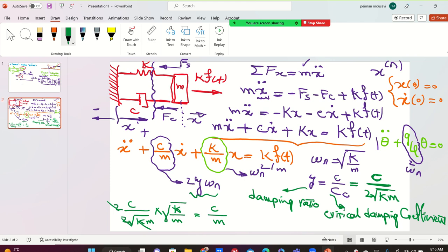You see that? Yes, exactly. Always, for second order systems. I am transferring the dynamics of the system from K, M, C to meaningful parameters. One of them is the natural frequency of the system. Another is the non-dimensional number, namely the damping ratio. On the other side of the equation, K over M is also the natural frequency squared.